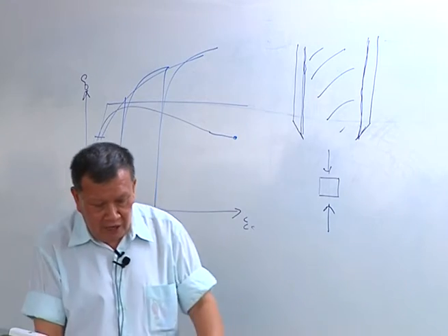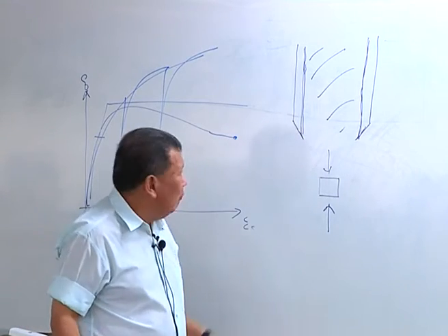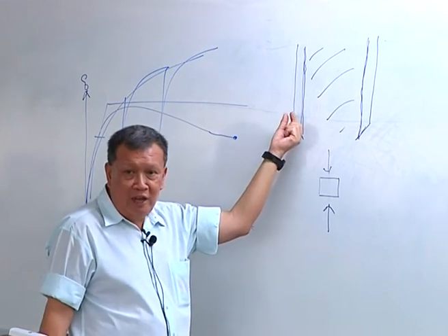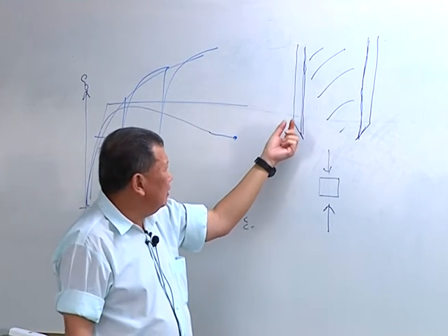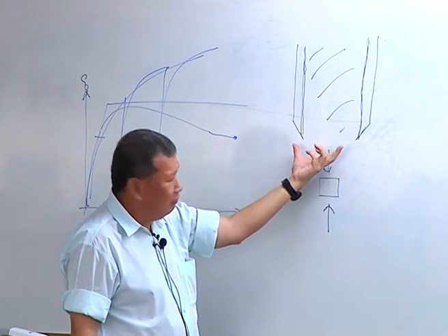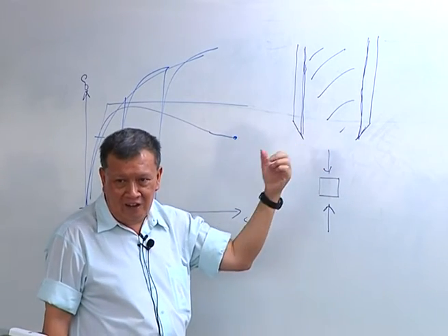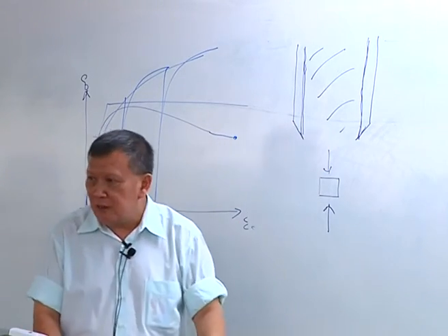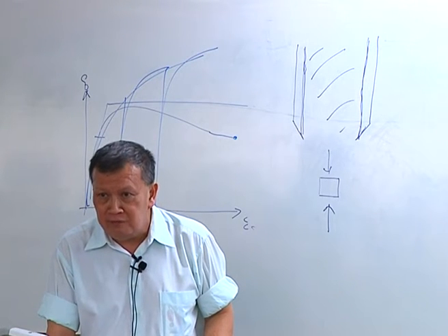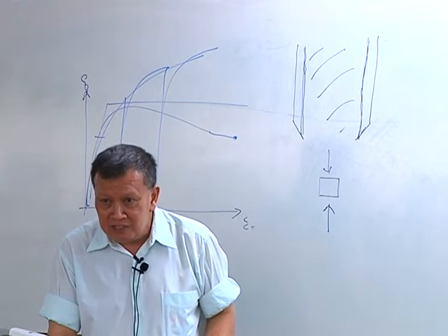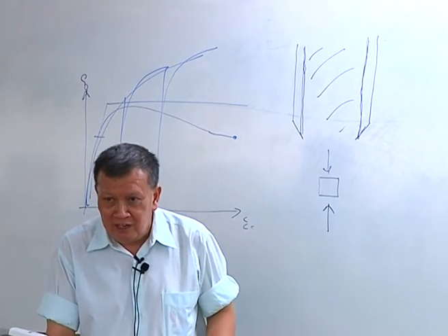All right, that's one. Now, there are other ways to do it, and one of them is, of course, to make this wall as thin as possible. Actually, the thing that is important is not the thickness of the wall, but the thickness of the wall relative to the diameter of this thing. Okay? I don't know the size of the sampling tube you use here, but typically in Singapore, we use 3-inch or 75 millimeters. Are you using 75? 70, 75, that's the kind of sampling tube.